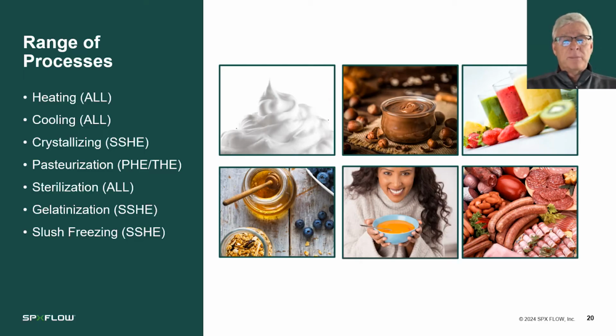Also, another type of process is what we call gelatinization. That's where we may take a water and starch, blend it, and then begin to heat it. And somewhere between 140 degrees Fahrenheit and 200 is when that process occurs of the hydration of water and starch together. And again, this is another area where we could maybe use dual technologies because of that. As you're hydrating the starch, it's relatively low viscosity. It's only when you're trying to cool it after the full hydration has taken place, you may need a scrape technology to get back down to the packing temperatures.